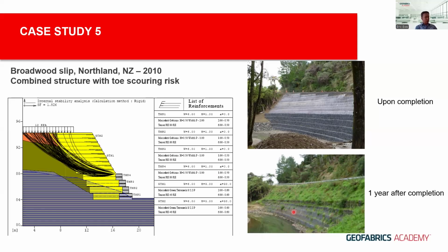The lower portion using gabion due to water concern, and the upper portion using a green Terramesh unit with vegetation over top to minimize the cost of importation of rocks and expedite the installation speed without stacking the rock at the top.